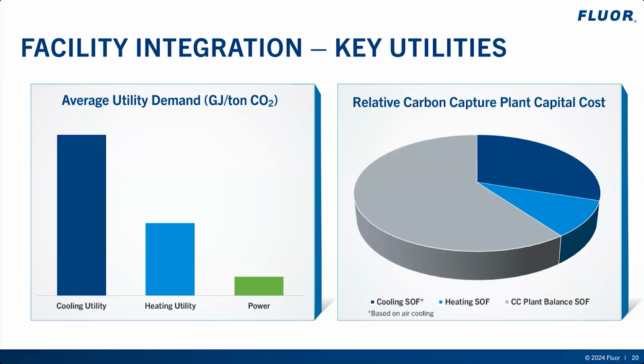Carbon capture facility power demand is mainly driven by the CO2 product compressor and the upstream flue gas blowers. It's also worth noting that in some jurisdictions, projects are looking to electrify the carbon capture plant design and completely eliminate fuel as the energy source for utility heating demand, again highlighting some of the unique project drivers that affect optimizing facility integration.